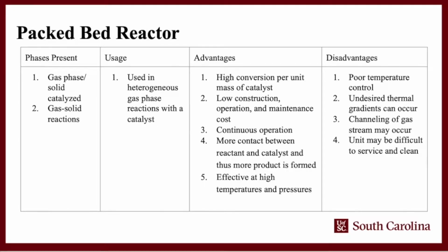The disadvantages are first that the temperature can be hard to control in such a system, and we can also get undesired thermal gradients and/or channeling of the gas stream can occur. And finally, the PBR may be difficult to service and clean.